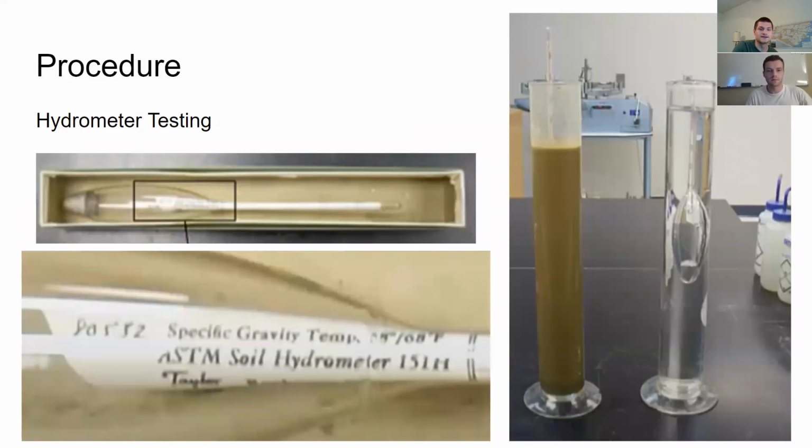Next, transfer the sample from the cup into a 1,000 milliliter graduated cylinder, making sure to wash the entire sample into the cylinder. Fill the cylinder to the 1,000 milliliter mark with distilled water. Another 1,000 milliliter cylinder with control solution will be provided for each group. Record the temperature and the hydrometer reading in this solution. This hydrometer reading will be the composite correction reading.